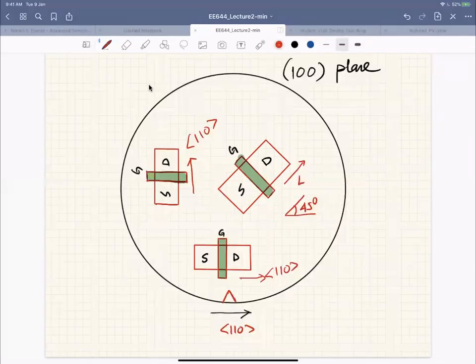You do different tricks to improve the performance of the transistor, right? So what do we mean by the performance of the transistor? We are mostly interested in current, because this is a voltage-controlled current source. If you give voltage, you get current in a transistor. So for a fixed voltage, we need to have high current, and current depends on charge times velocity.